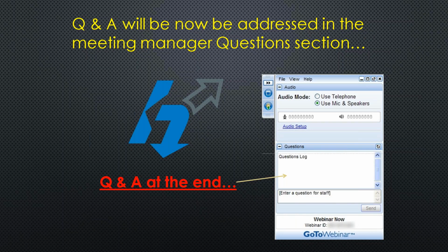Yeah, each one of those faces gets that exact load. So if you put 100 pounds in there and you do not select total force, if you've got 10 faces selected, each face gets 100 pounds. So when you select total force, then that 100 pounds is broken up amongst those 10 faces. So in that scenario, it would be 10 pounds per face.